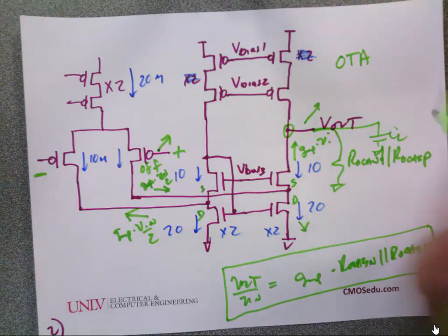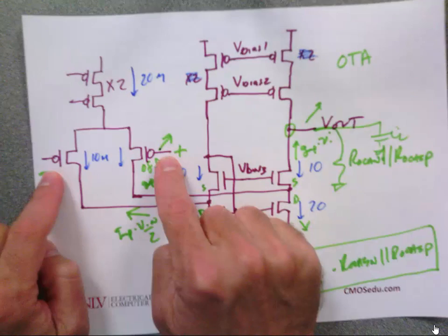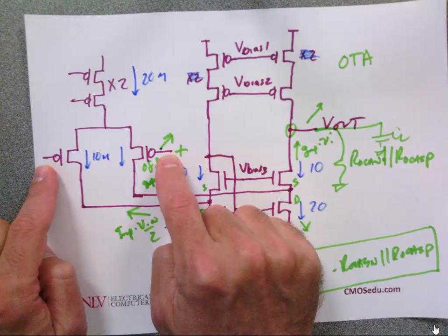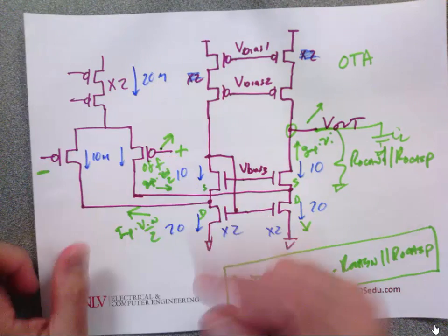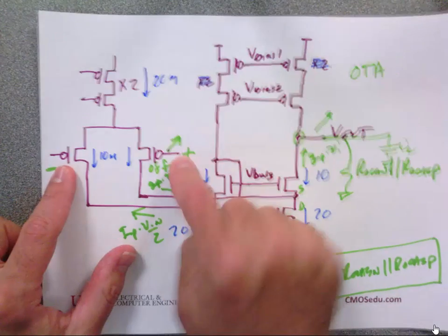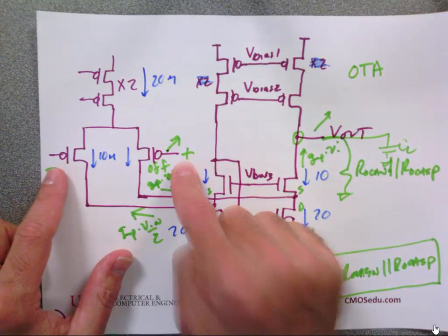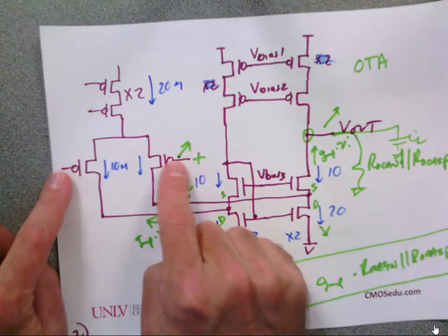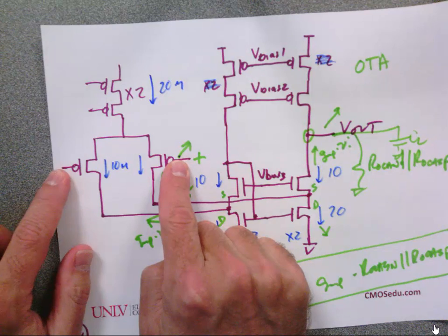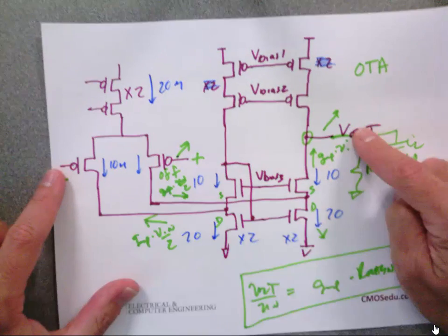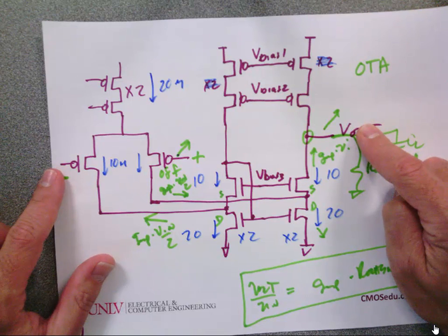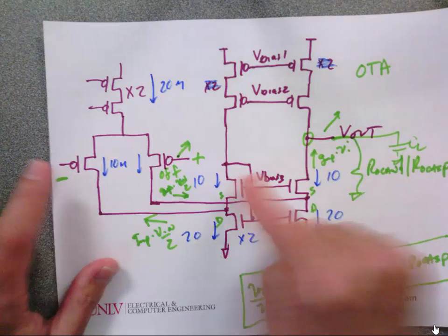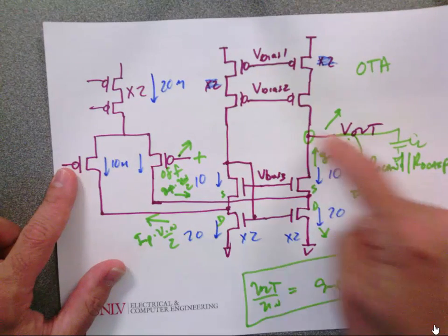Okay, just before I go any further, what's the maximum input common mode range? VDD minus 2 VSD sat. Yay. VDD minus 2 VSD sat minus VSG. It's not very high, right? But this is at VSD sat. So these can go below ground and they'll still be functioning. Unfortunately, the output's limited to 2 VDS sat, so about 100 millivolts. So even though I put it in the follower, I can't go negative with these, because the output can't swing negative because I need 2 VDS sat.